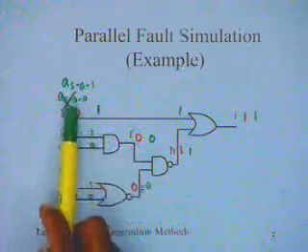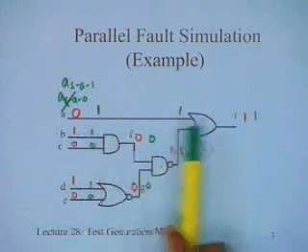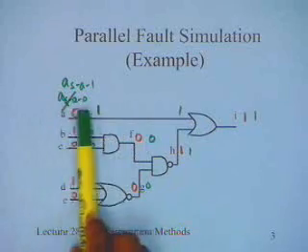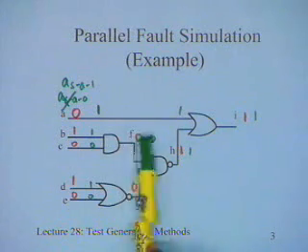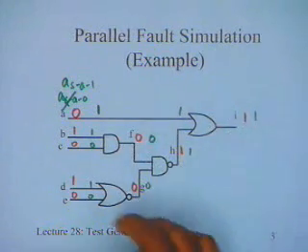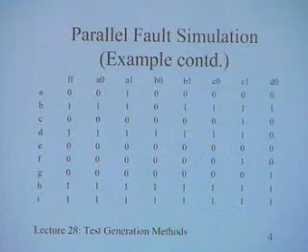That is, with the true value set and with the faulty value set. And I can do this not just at the primary input, I can also do it, for example, with F stuck at 1 here. I can start the evaluation there. Of course, instead of 0 I will write a 1 here, because this is stuck at 1, this is the faulty mode with F stuck at 1, and do the evaluation. So for example, this particular table shows this parallel fault simulation.